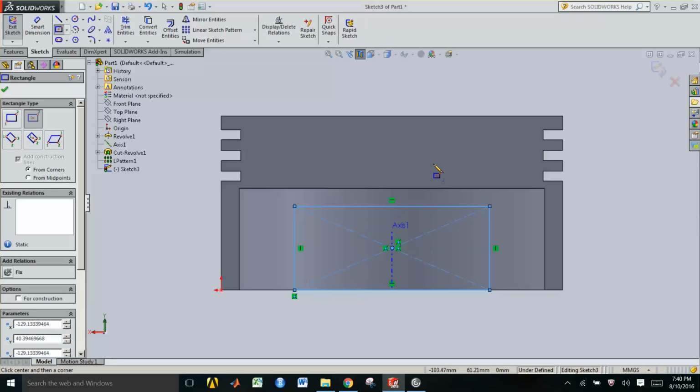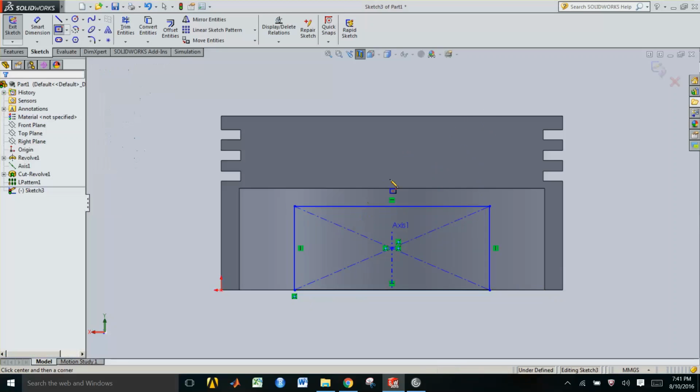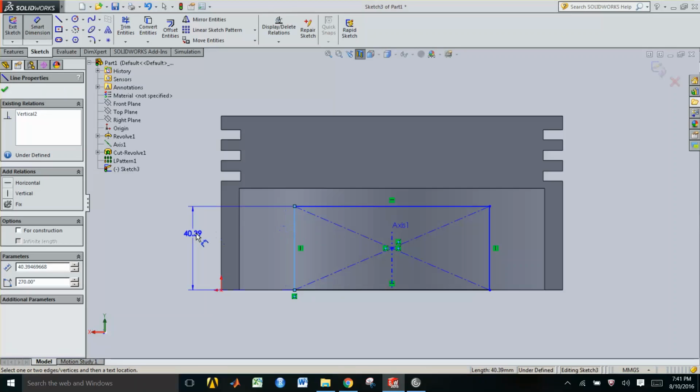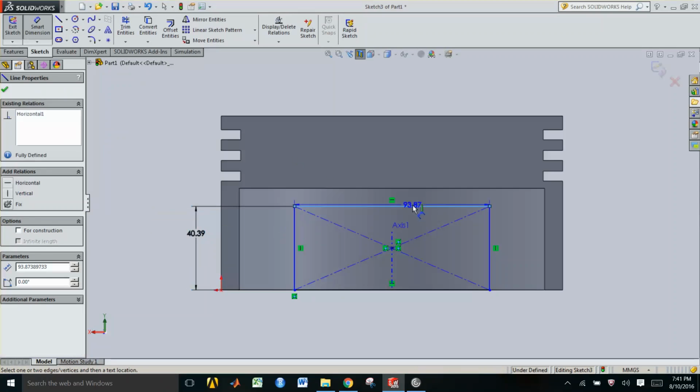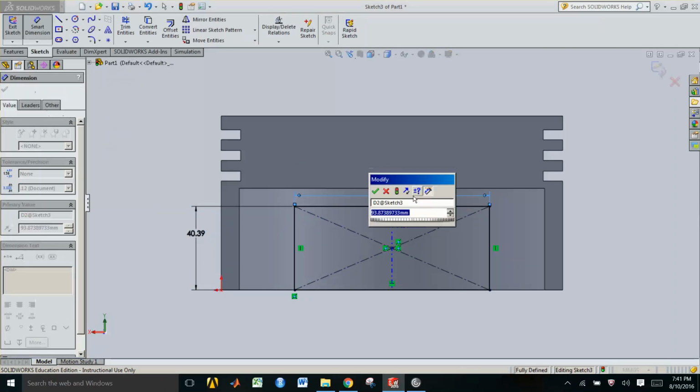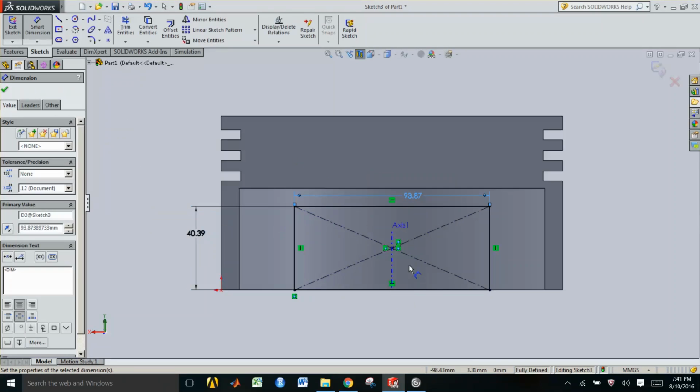So what you do is you just basically draw a center rectangle right there. Okay, and the center rectangle looks pretty good. I'll give some dimensions to you. There you go. I'll give you that dimension. Notice that it needs to be sitting right here, and it needs to have its center on the axis that we just defined not so long ago. I'm just letting you know that. All right, so cool. So we just drew it.